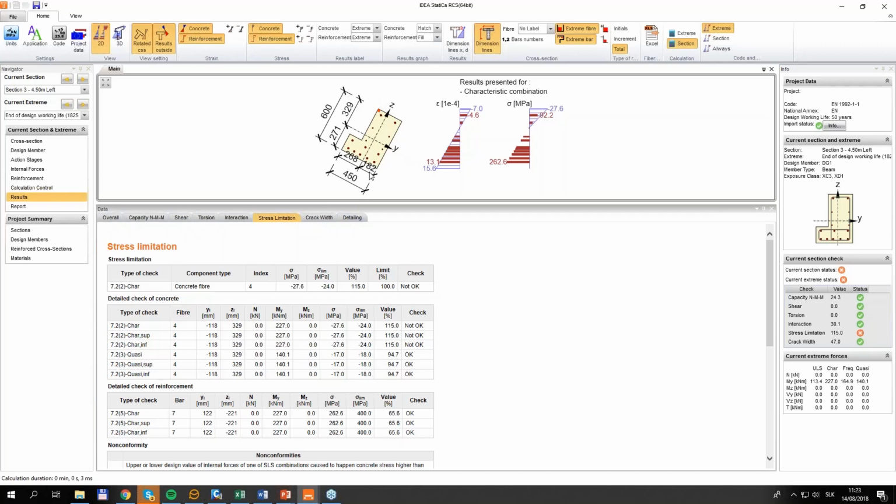And as I see, the problem is that it's tilted because of the non-symmetrical section, right? And it's very big in the compression fiber, or compressed fiber, and I can help it with some redistribution. So if I add more reinforcement in the most effective area, I can help that.